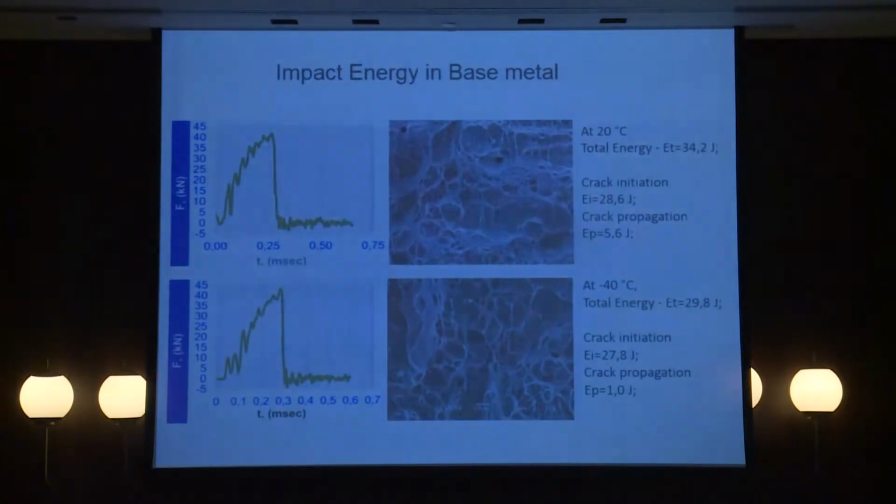The fracture surface is mixed brittle and ductile. At minus 40 degrees, the total energy is approximately 30 joules. Crack initiation energy is 27, and crack propagation energy is 1 joule.